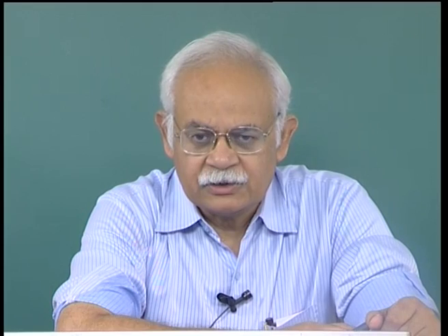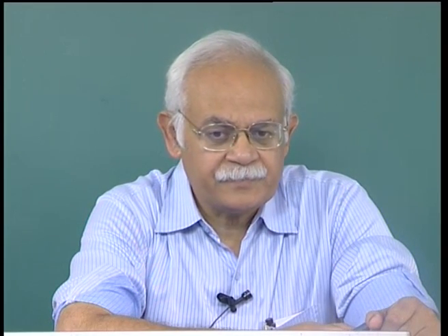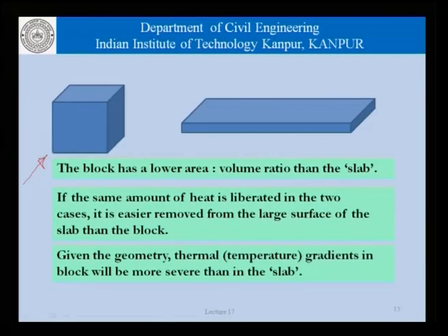And the surface area we saw in the case of slabs is much larger than that of the cube. We had also discussed that these concretes are cast against a certain previously placed concrete at the bottom, and then there is the formwork around this block, and this surface is exposed to atmosphere. So, depending upon the exposure conditions, the characteristics of dissipation change depending on the characteristics of the surface or the boundary conditions of the surface.